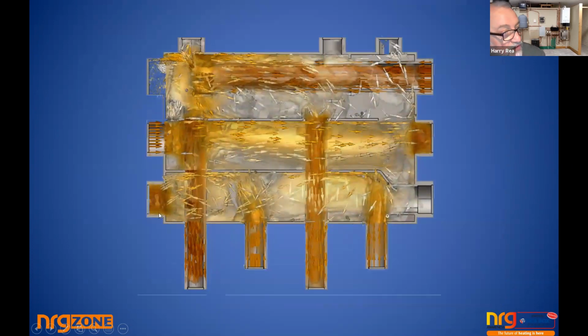So now the heat pump is delivering across to here, but guess what? The gas boiler pulls it away before it gets up to here. The gas boiler takes 40-degree water and raises it up by 20 degrees, which is tremendous for a gas boiler to have that efficiency.